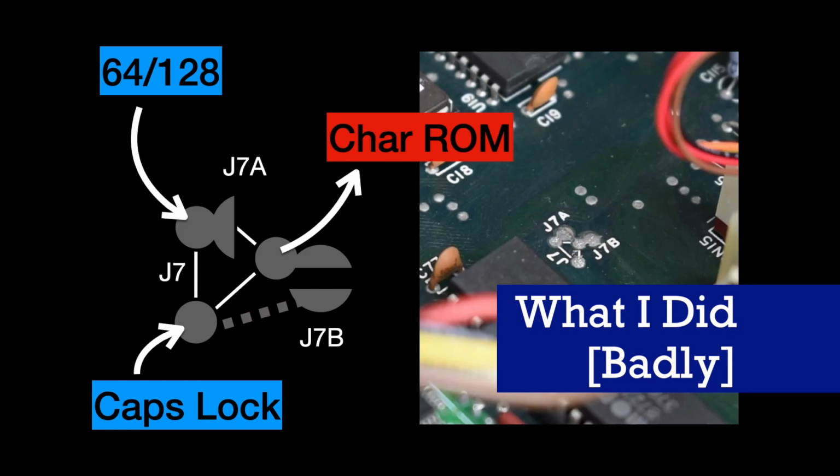So after I'd broken J7A, I could obviously no longer short it, so I had the idea that I could put a wire between the top left and the bottom left terminals, thinking that would connect the 64128 line at the top to the character ROM output on the bottom left. But of course what I was actually doing was connecting the caps lock key to the 64128 line. So the computer would start up okay until I pushed the caps lock key, when it would completely crash. I couldn't work out why, but of course in retrospect now I know that that's what was going on.